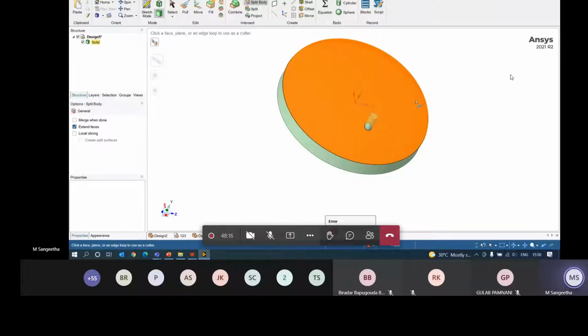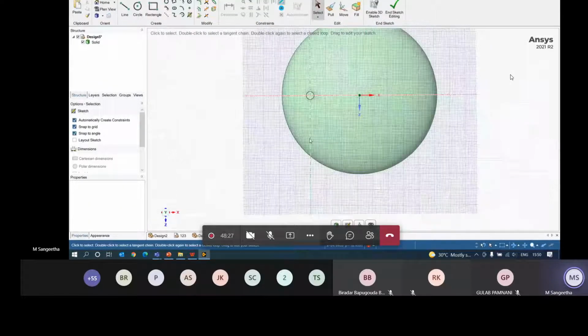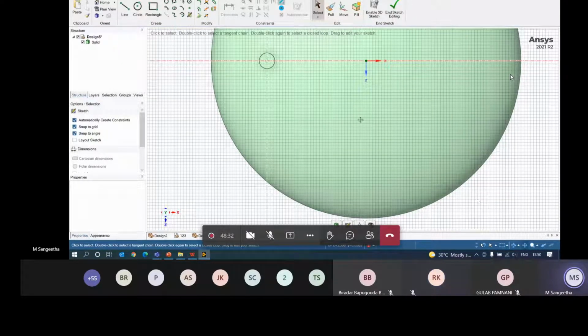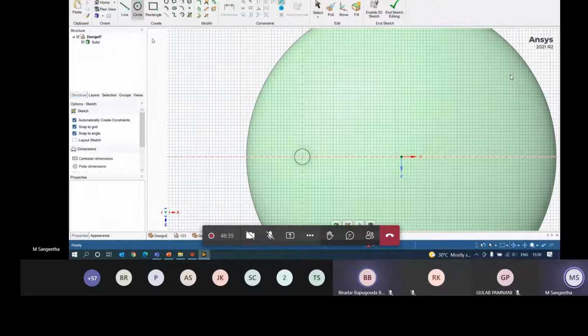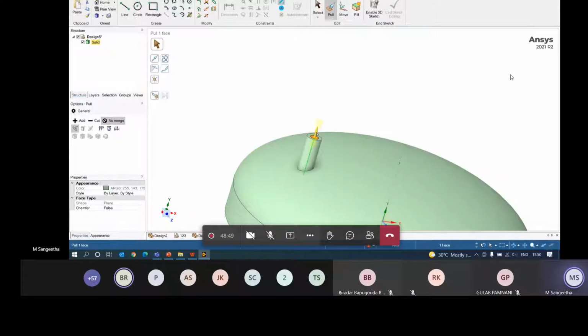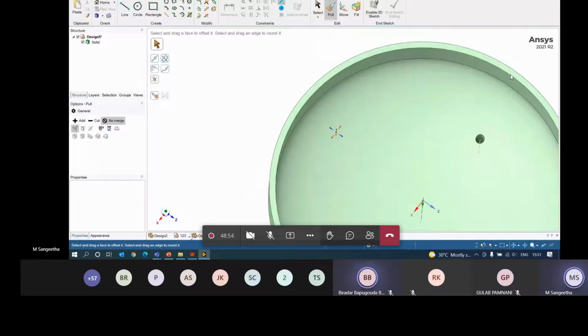Then afterwards you need to exit from the tool that you're using, select the surface and get back to sketch mode, plan view, into zoom, control plus, and start designing. Okay, so we'll come back to the solid mode now and we'll try to remove it. Okay, so when you set like that, you are able to get a hollow here, right?